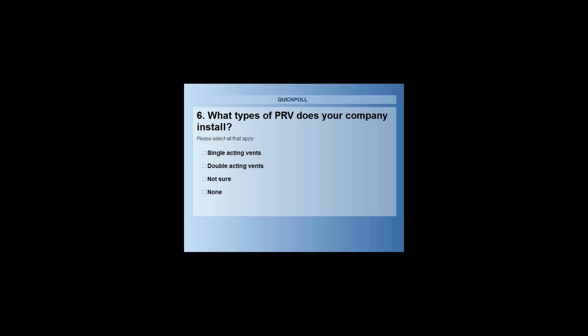Now, someone asked me a question about calculating the volume of the space we're venting into. What's more important than the volume of the space we're venting into, because that line of thinking assumes that the volume we're venting into is airtight, and it never is, is to measure the leakage of the volume we're venting into. Typically the volume we're venting into is much larger than the space we're venting from. In a case like that, you get some credit because of the volume you're venting into, but not much. But I think more importantly is how leaky is the space we're venting into.